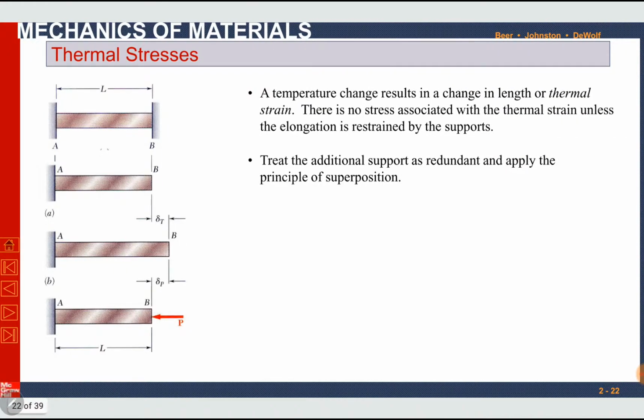Moving forward, our next topic is thermal stresses. Thermal, it is very clear, it is related to temperature. A temperature change results in a change in length or thermal strain. Whenever the temperature rises, there is a thermal elongation, and whenever temperature falls, there is a thermal contraction. This elongation divided by original length, or the thermal contraction divided by the original length, is thermal strain.